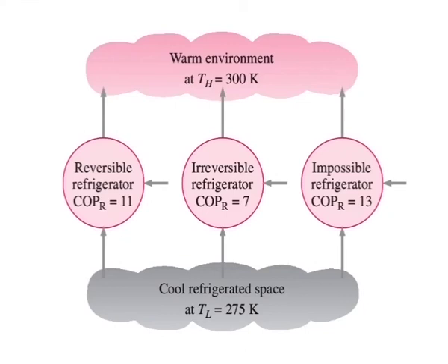As the temperature of the refrigerated space approaches 0, the amount of work required to produce a finite amount of refrigeration approaches infinity and COP_R approaches 0.